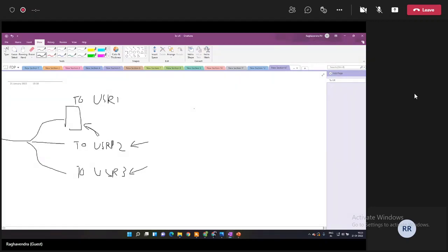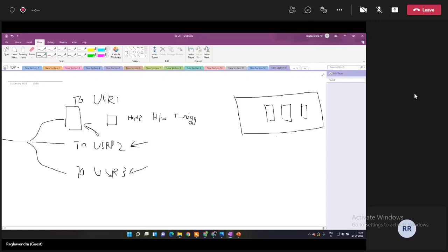So what we do in this scenario is, in the software itself, we write a piece of code that says to have hardware triggers. Now, I mentioned that the PXI system has cards where your MXI cards go over here, your PXI chassis system. If you look at the back of this system, there are actually a couple of lines that are running, which are called trigger lines.